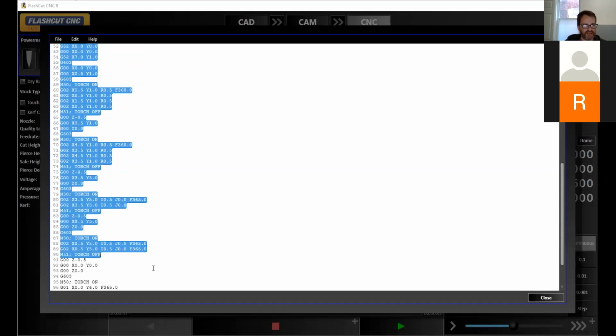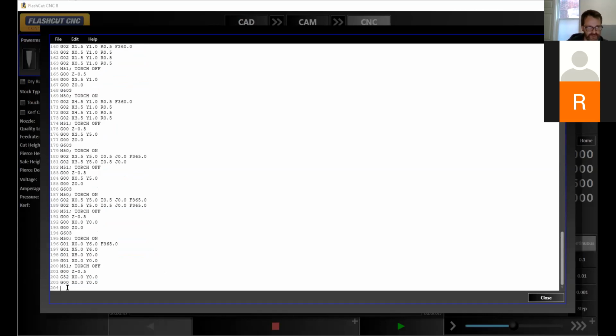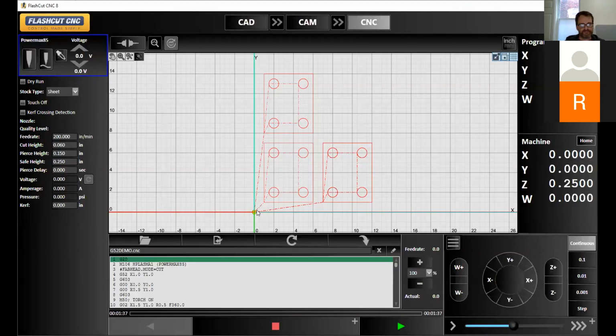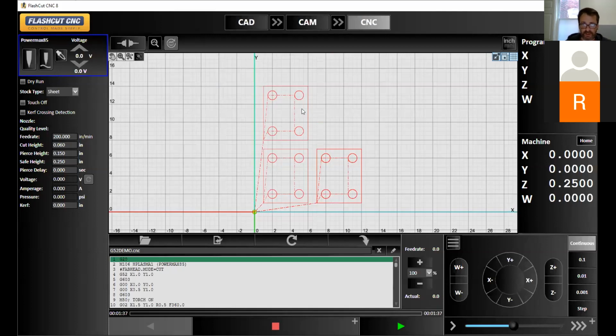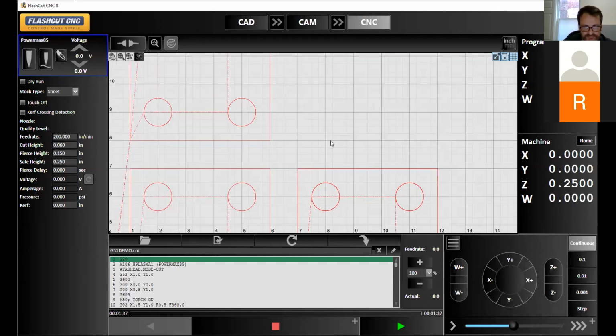Now, since we have a code right next to it, we're probably going to end up with 2 more. Control C, Control V, save it. So now we have another one. And we can keep this on and on. We can pick different coordinates in the grid and keep duplicating these parts. Works a lot like beginning grid, except you're just using a G52 code. You're picking new coordinates and you're implanting those coordinates.